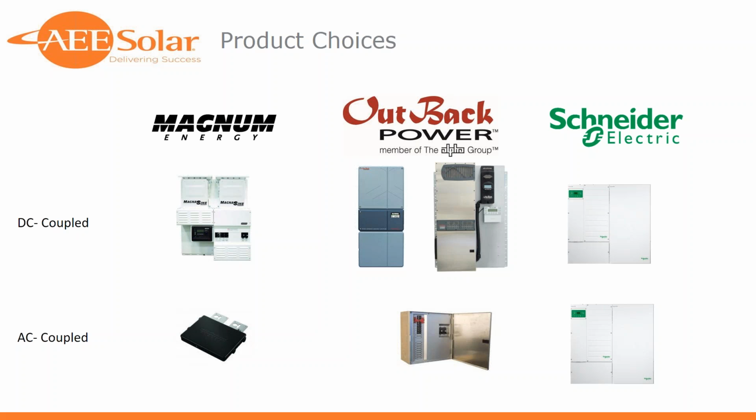You can put all of your circuit protection in there, and I've got the older version. The newer version is, in my opinion, much more conducive to wiring and practical application for people with real sized fingers. The older version was pretty tight in there. Similarly with Schneider Electric, you can AC couple with XW Plus, XW Pro. Probably wouldn't recommend it with SW.